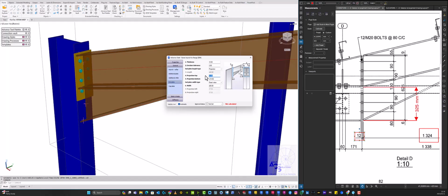So in steel detailing, there should be an allowance for welding. So you cannot have your end plate flush with the top edge of your flange. For example, on your rafter, you can't have the plate flush with the top edge of your flange for the rafter. You have to either increase by a certain distance so that you can give allowance for welding, or reduce a bit so that you can have that allowance as well. So it is up to you. So usually I like to reduce the plate by 6 millimeters so we can allow for welding.